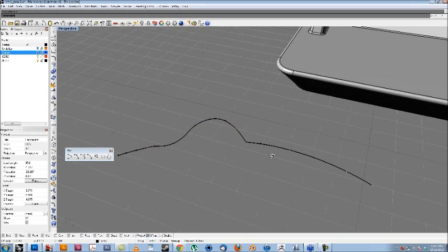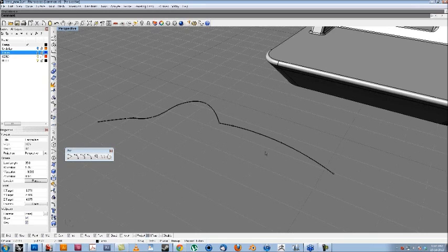One thing I would say, and this was a great topic that came in on a webinar I was listening to on T-splines, was to make sure that you really need the control point or the edit point. A lot of times people think that by putting in a whole bunch of edit points or control points, it's going to help you define what you're trying to show. Oftentimes you only need like 3 or 4 control points on a curve to really be able to describe it, unless you're doing something that's highly organic and has a whole bunch of little kinks and puckers.